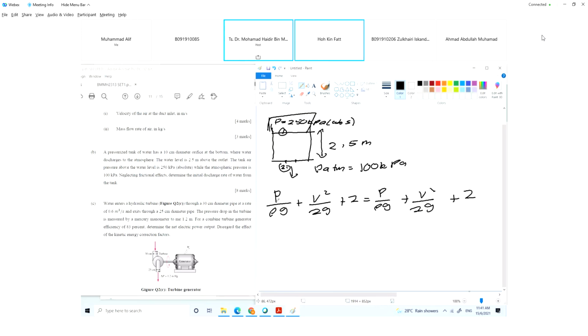You want to ignore the pressure. Okay. So the situation where we can ignore the pressure is when the pressure is equal to P atmosphere. You can differentiate between point 1 and point 2. At point 1, the pressure is 250 kilopascal, and this is absolute pressure, where the P atm is 100 kilopascal. So at point 1, the P is equal to 150 kilopascal if it is the P gauge. If you want to cancel it, it is at the point where P gauge is equal to 0. So at point 1, P is equal to 150 kilopascal gauge. You cannot cancel P.